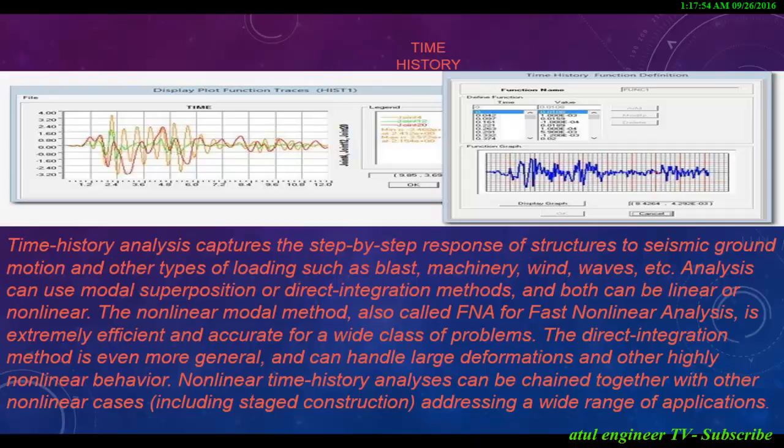Time history. Time history analysis captures the step-by-step response of structures to seismic ground motion and other types of loading such as blast, machinery, wind, waves, etc. Analysis can use modal superposition or direct integration methods, and both can be linear or nonlinear.